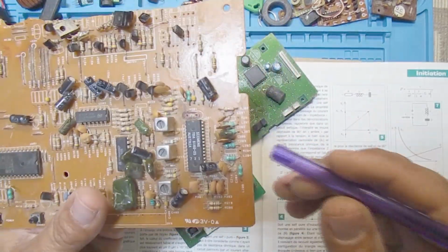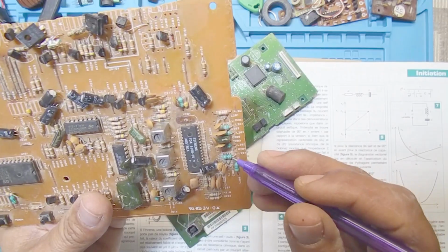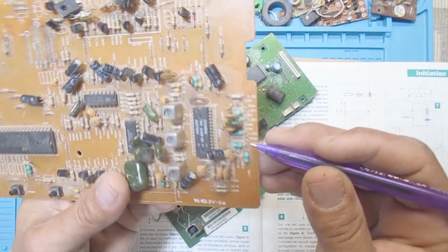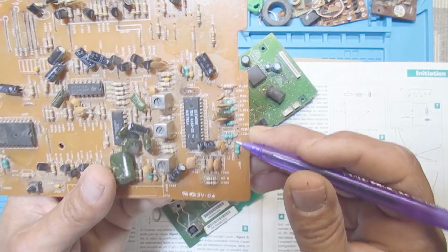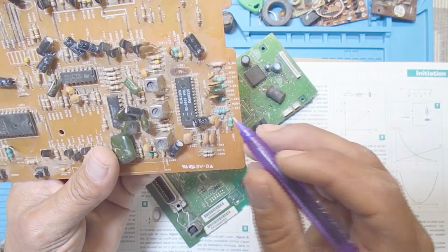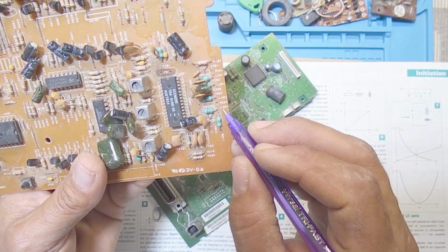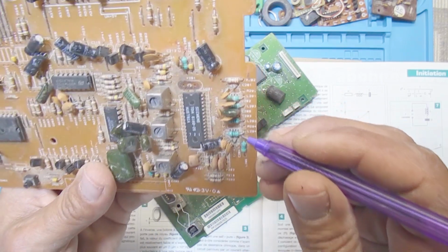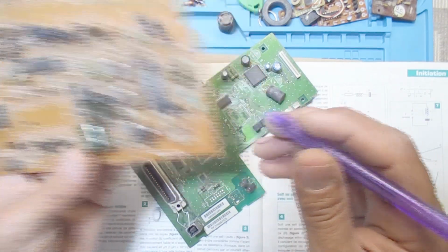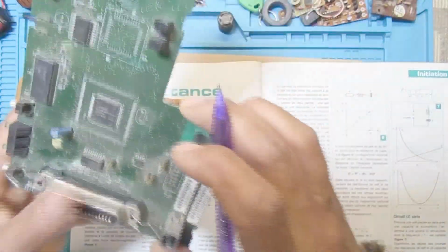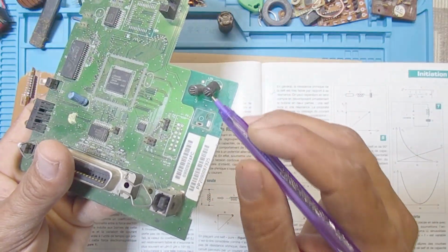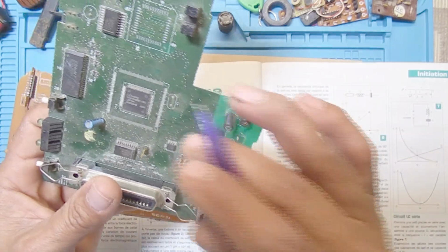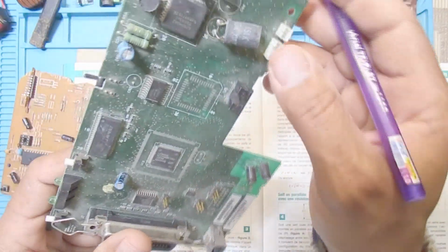Here we can find a through-hole inductor. It appears as a resistor, but it's an inductor. We can differentiate it by the symbol. We have L284, and we have here the symbol of an inductor. Those are the choke inductors. They are used to block the high frequency from entering the board or from escaping the board.